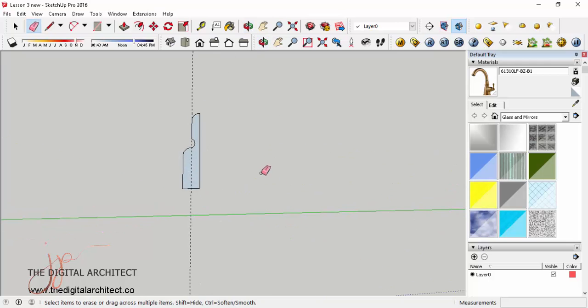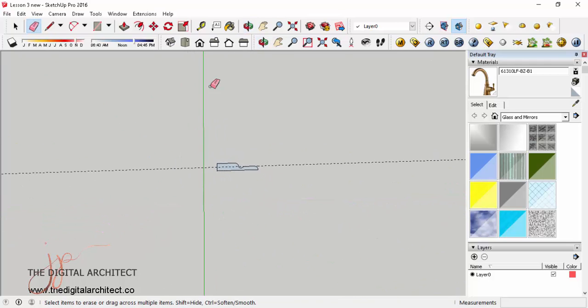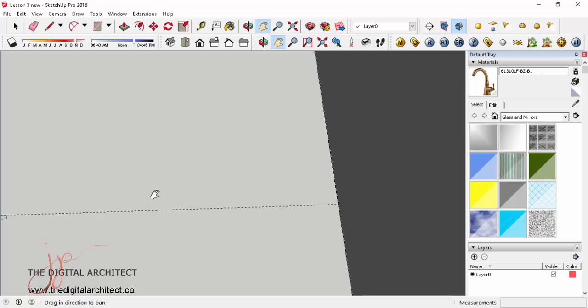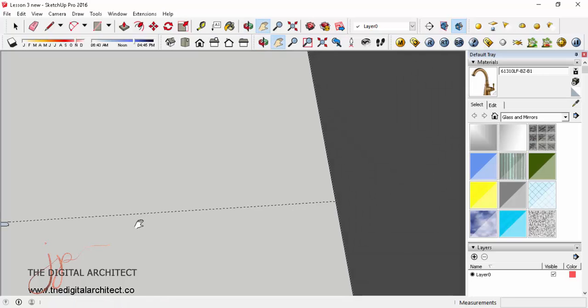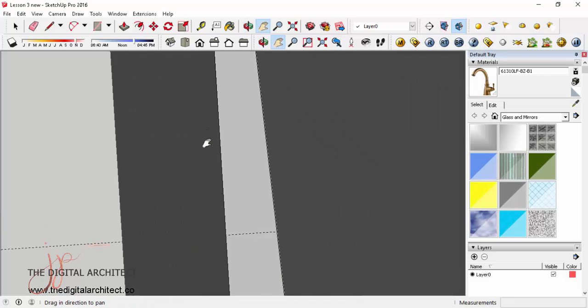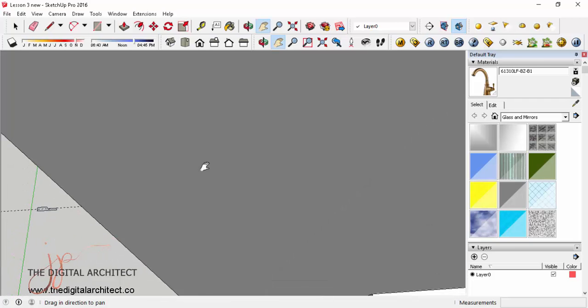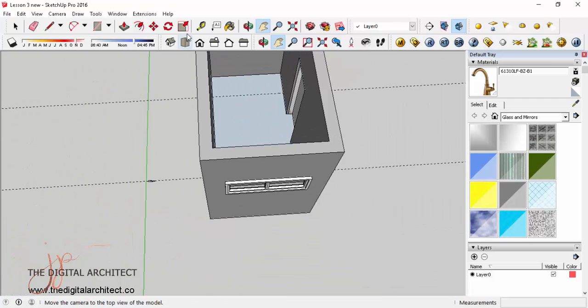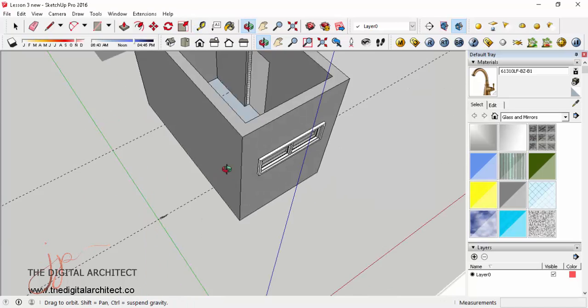So remember, the width of the wall is 1,800, or if you're not sure, that's okay, but I can remember from lesson 1 that the width is 1,800. Let's check again. To check, just click on tape measure, click on one side, and then click to the next side. It will give you the measurement, which is, I'm correct, 1,800.